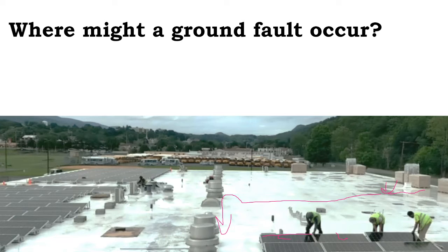Well, that's better than having that live voltage up there, and then the thing that does touch it to ground is you. So we have grounding of metal parts requirements for the ground fault to occur through to ground to clear it. But if that power source is still operating and that ground fault is still running, we really need to pay a little more attention to what actually clears a ground fault.